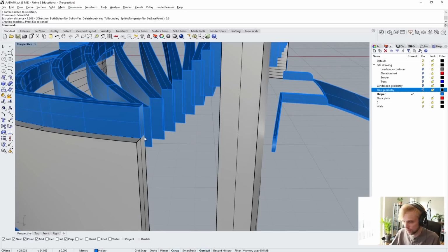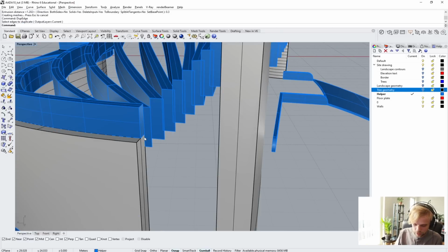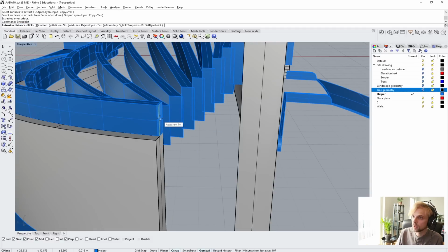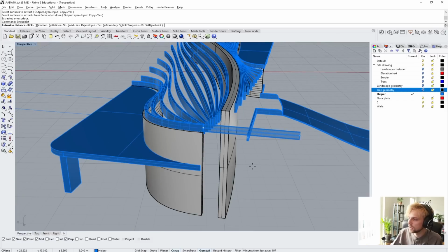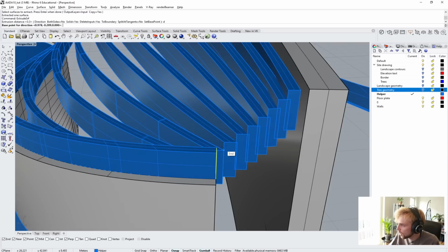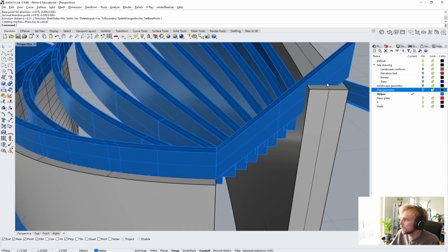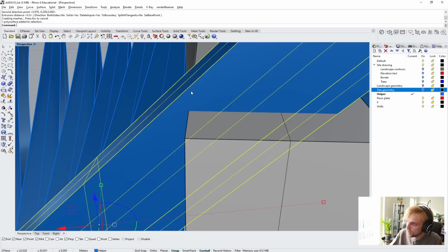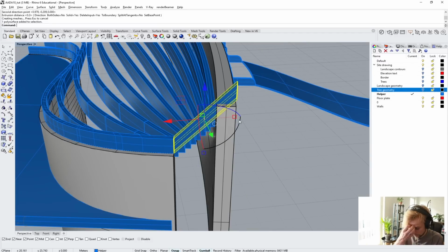Upwards, then I will use duplicate, no, not duplicate edge, but rather extract surface. On the surface right here, I will extrude the surface, but I will not be extruding it in this direction. Rather, I will describe the direction for it. So D, enter, let's say a direction between these 2 points, like that. And then after I'm done, I see that it's a little bit too steep because it kind of goes beyond the top of this middle wall here.